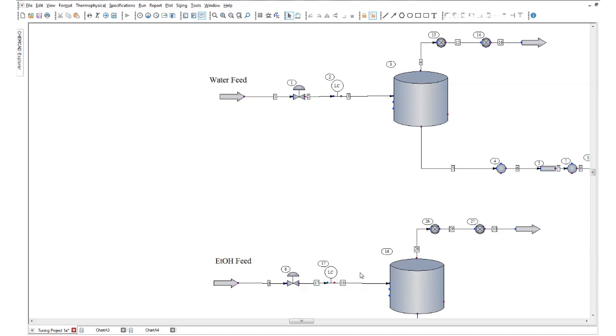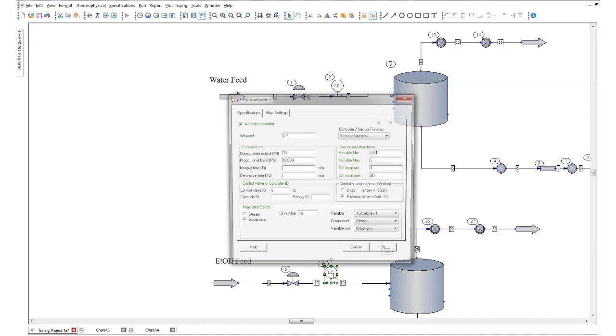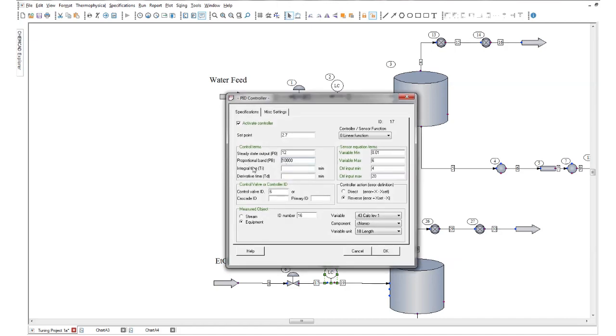So what you want to do is use that same Ziegler-Nichols technique to adjust the proportional band, and calculate the integral time constant and the derivative time constant by changing my proportional band. Start off at a high value and make it smaller until we see the oscillations begin to decrease.